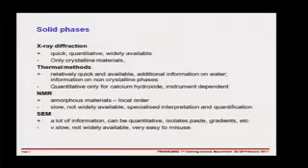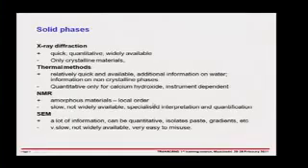Really, they're only used for quantifying calcium hydroxide. NMR has been very successful because it can be used on local materials, because it looks at local order rather than long-range order, but it's very slow. Typically, the kind of measurements I've shown you can take up to a day to acquire the spectra. It's not widely available, and you really need specialist knowledge for interpretation and quantification.